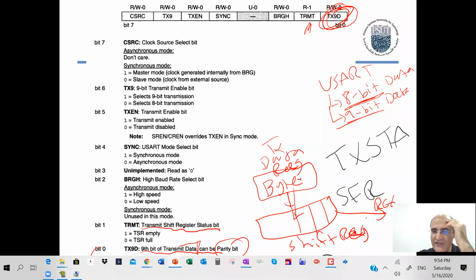So when you want to transmit a byte, you write it here, it is automatically sent to the shift register and starts shifting, transmitting. Now, whenever this shift register has data in it, you cannot transmit anything new, right? You cannot write another byte because you're going to interrupt the previous byte. Because it's not a one shot. You write the byte in this register in parallel, right? But when it's moved here, it starts sending out in serial. So slower, much slower. So when this shift register is busy, it's full, you cannot transmit a byte. You need to wait for it to empty, then you send the next byte. When it's empty, you send the 3rd byte. When it's empty, you send the 4th byte.